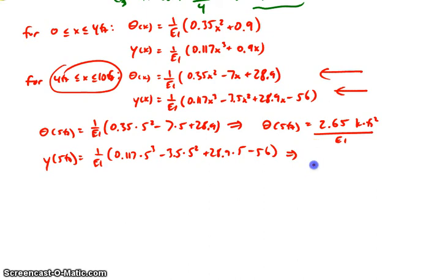We do the math and we get y at 5 feet equals 15.6 kip feet cubed over EI. Now units, the numerator of this term, or any kind of deflection term, is going to be in units of force times distance cubed. That way when we divide by EI, we get simply a distance, which makes sense because deflection is going to be in terms of length.